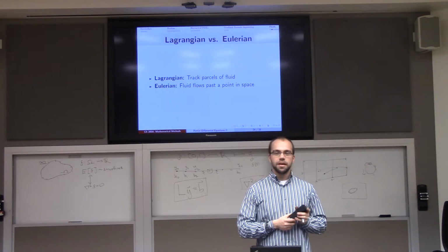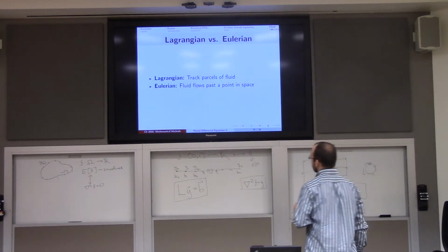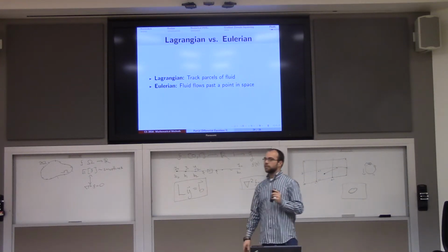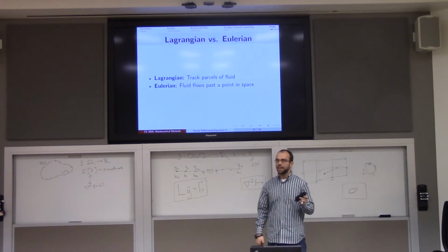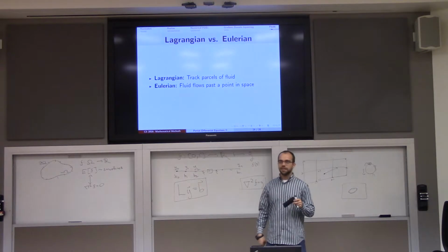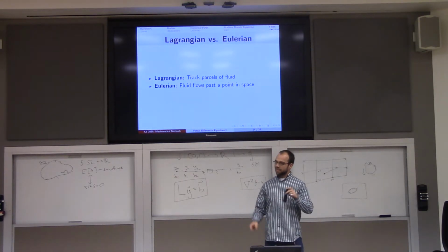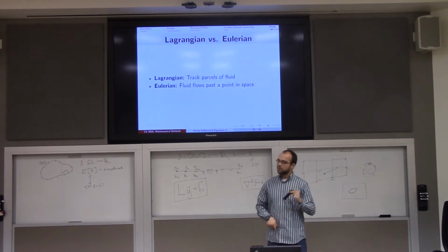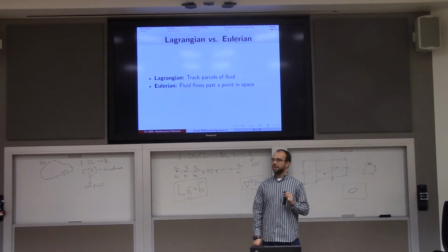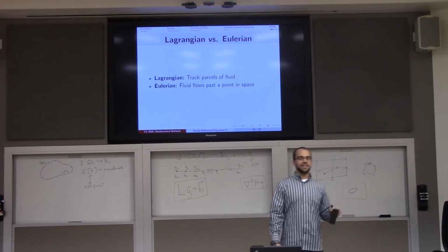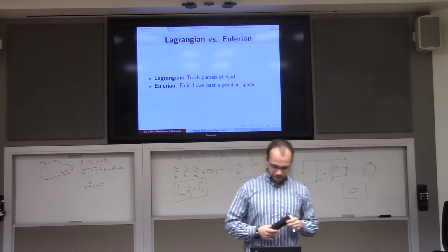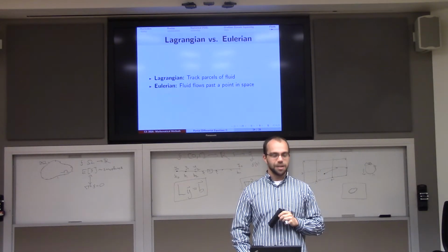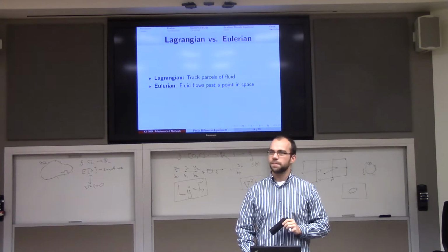Contrastingly, an Eulerian fluid says that we can change our reference point in physics. You can either track the water as it moves around, or I can say, I'm going to stand at this point in my fish tank and watch water go past me. And so you can think of the velocity of the water as a function of time in 2 ways: either the velocity of the water particle as it's moving around, or the velocity observed as I stand at this point. For example, maybe I have one of these wind collectors and I collect the wind motion at different weather stations. That would be an example of an Eulerian discretization. So Eulerian things tend to live on grids, Lagrangian things tend to track particles around.